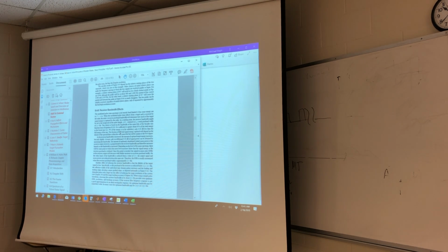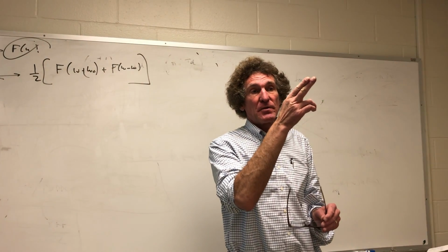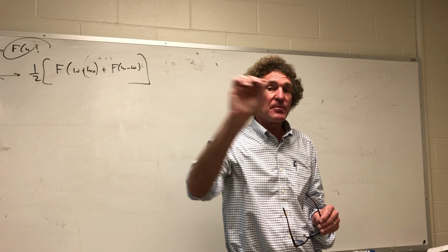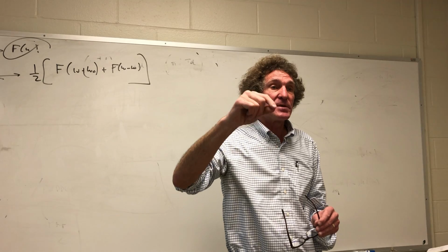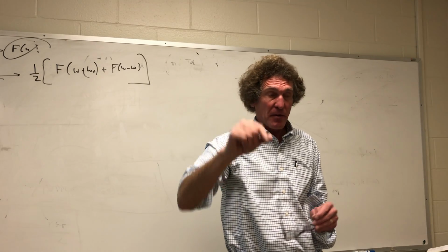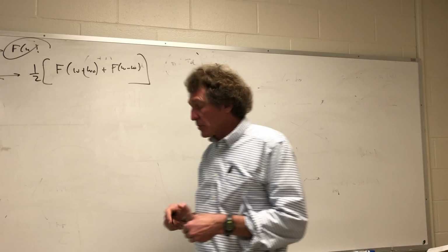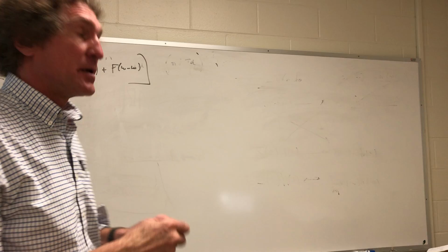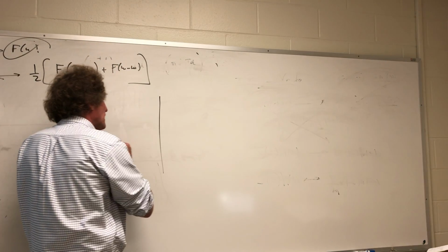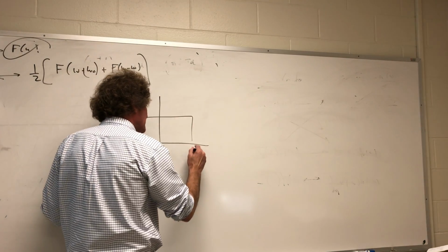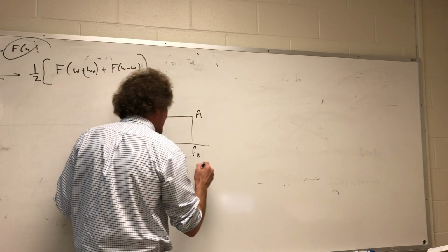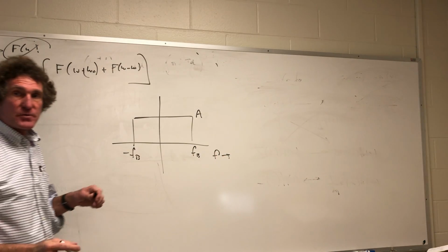Amplifiers, in this book, he's assuming amplifiers have a flat amplification ability. In other words, if you put in a certain power P1 at frequency F0, the amplification would be the same as if it was at 2 F0. Well, over a bandwidth, and at baseband, really this is done probably at the intermediate frequency, but this is what we'd like at baseband. If this is F bandwidth here, F minus F band, we'd like it to be flat with just A, and this is versus F, right? But here's what you really get